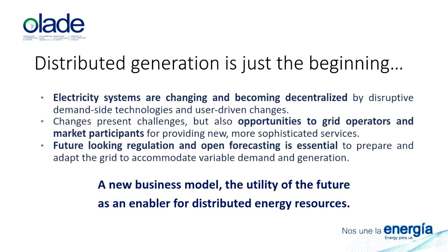There's interest for implementing automatic volt-var controls in solar PV inverters, for example, or automatic derating of solar inverters, so that when they sense that the power factor is going outside of the limit, or when they detect that the voltage of the grid is going outside of the allowed range, they can reduce their generation automatically and avoid that impact.